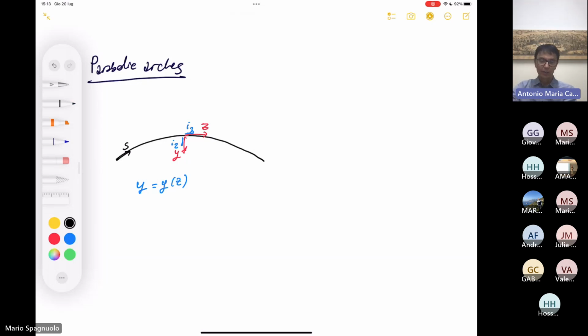We need to convert, transform our basic equations to account for the change of variables and to assume z as the independent variable instead of s, that is along the beam axis. For doing this, we initially have to introduce some geometric preliminaries, so we have to switch from s to z. And so we will start by computing the relationship between ds and dz.